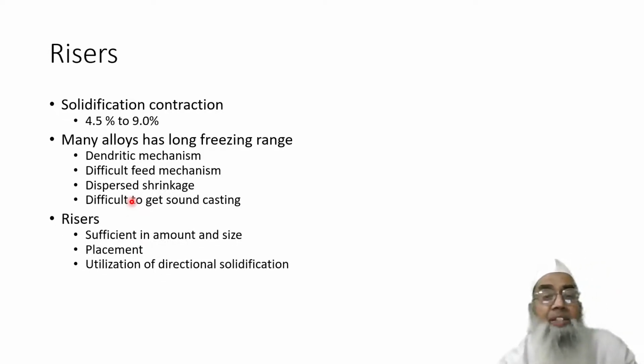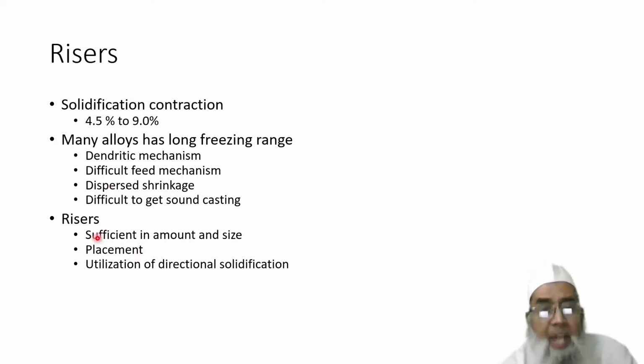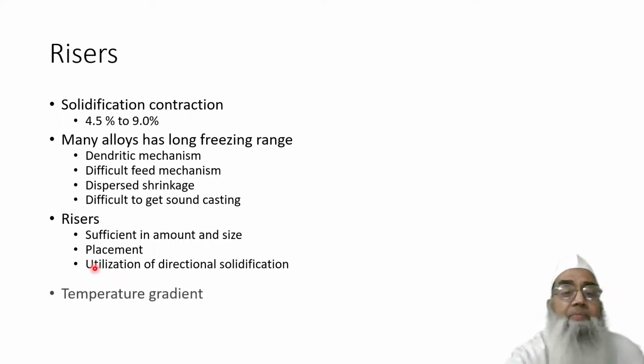Therefore, the riser has to be of sufficient size and placed in a very efficient manner, and can be of multiple types, and this only can give directional solidification.